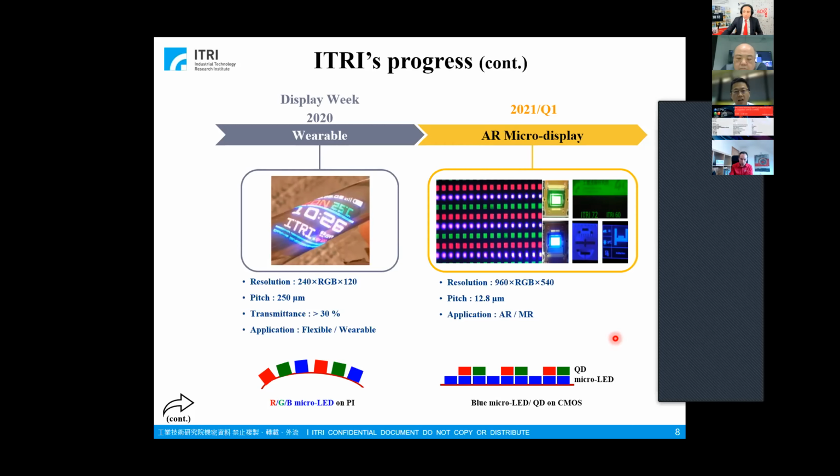For AR high PPI micro display, the integrated single color micro LED array with a color conversion layer has been treated as one of the solutions for high resolution full color displays. It is integrated with simple circuits, which bring multiple functions, and the overall volume is compact.